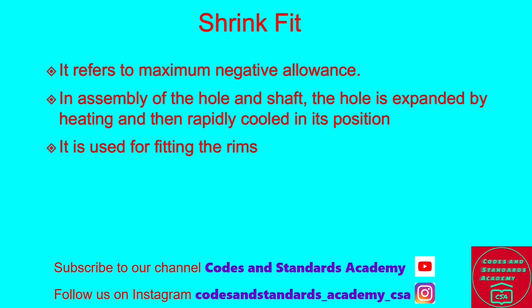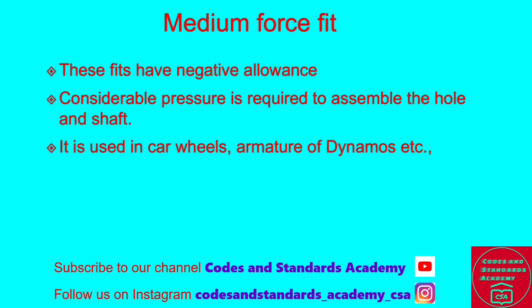Shrink fit. It refers to the maximum negative allowance in assembly of a hole and a shaft. The hole is expanded by heating and then rapidly cooled in its position. It is used for fitting of rims. Medium force fit. These fits have negative allowance. Considerable pressure is required to assemble a hole and a shaft. It is used in car wheels, armature of dynamos, etc.